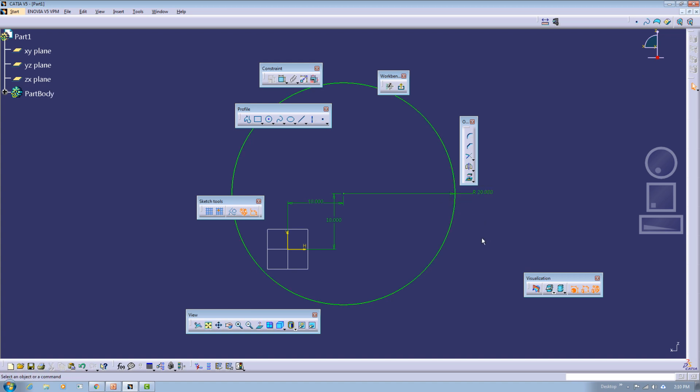Okay, but did you see that I did not apply any of these constraints, but they were created automatically? Now, it happened because this particular tool, the dimensional constraint or implicit dimensional constraint, was selected. So when this tool is selected, it will automatically create dimensional constraints as well. Let me just demonstrate this to you while turning this off.